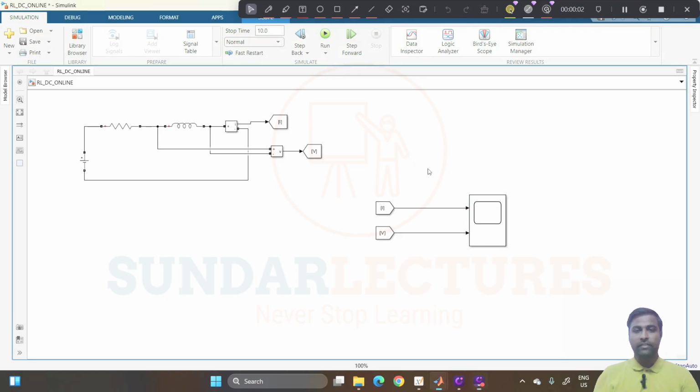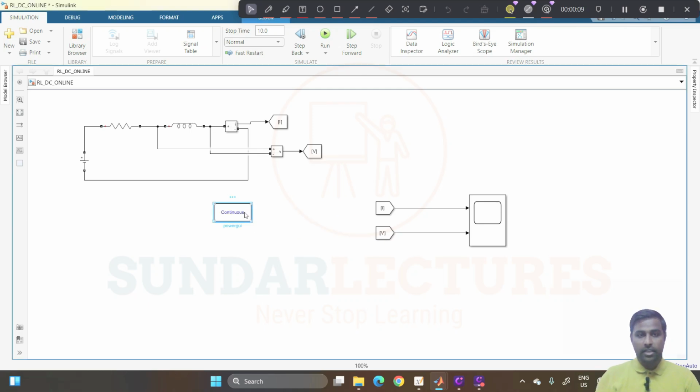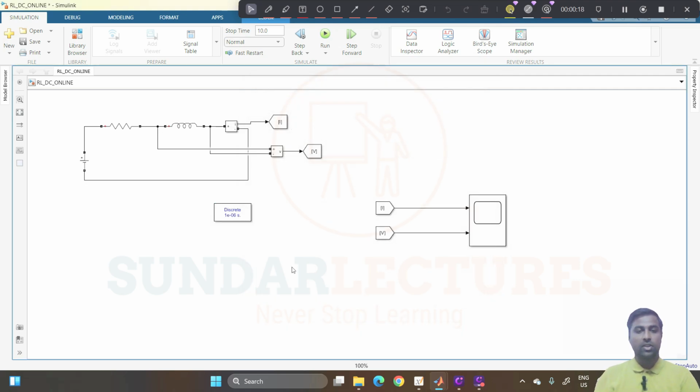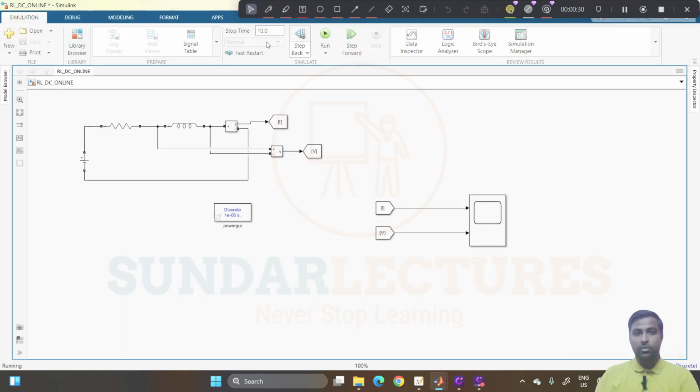Now that's all we have done. Again double click here, we need powergui. Click this one, go inside, double click, set it to discrete and make this value 1e-6. That's all. We have done everything now. Now we try to execute the circuit. Click this run button and it will be running now. The stop time we have given is 10 seconds, so it will be running to 10 seconds.